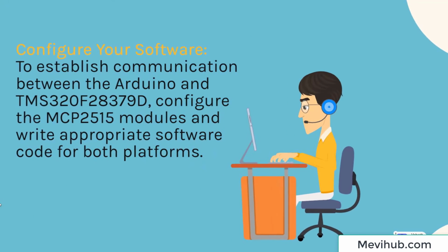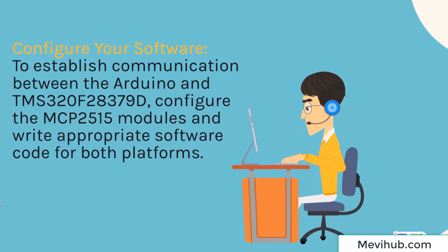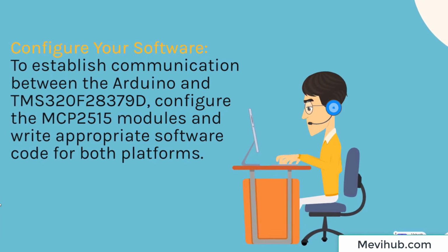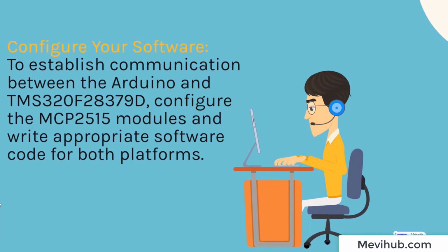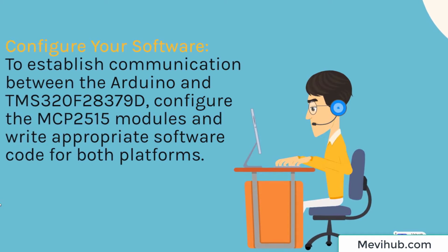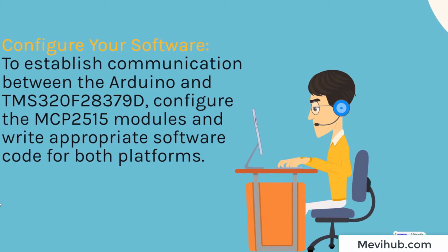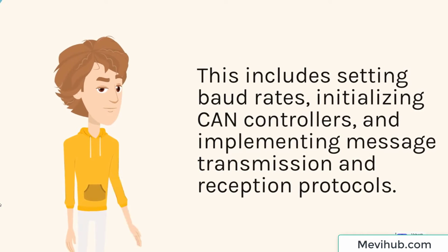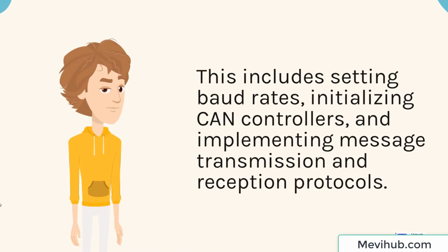Configure your software. To establish communication between the Arduino and TMS320F28379D, configure the MCP2515 modules and write appropriate software code for both platforms. This includes setting baud rates, initializing CAN controllers, and implementing message transmission and reception protocols.